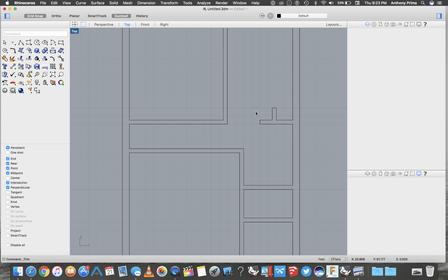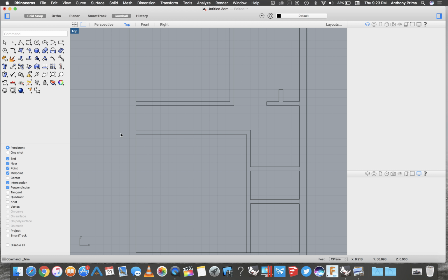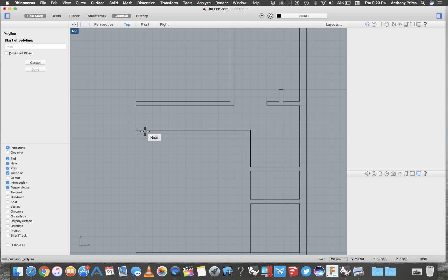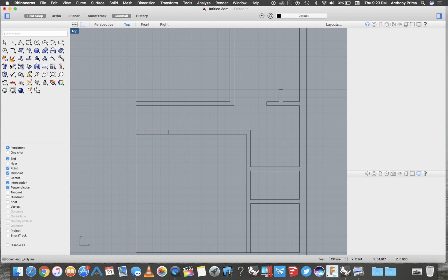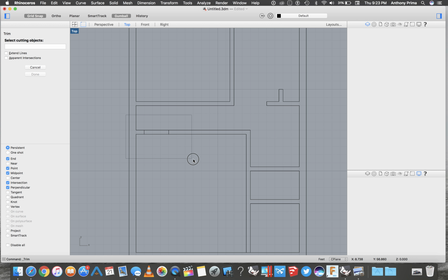And this is essentially all there is to drawing the interior partition walls, which are these 0.5 foot thick ones, and the exterior partition walls. In the other videos, we go over things like how to create openings. So if I wanted to create a 3-foot door over here, I could just draw a line there, count out my 3-foot opening, and then using the exact same tool,